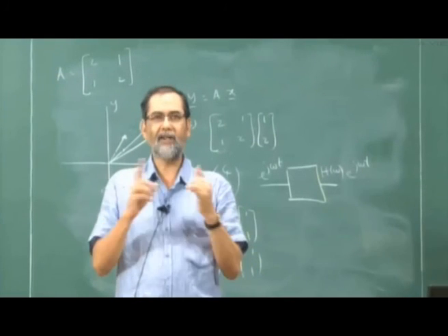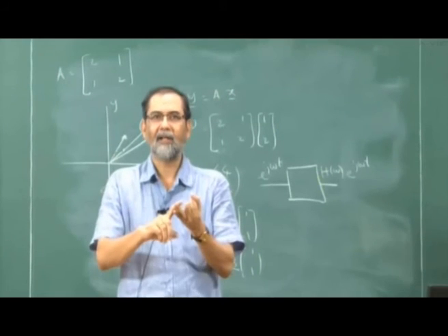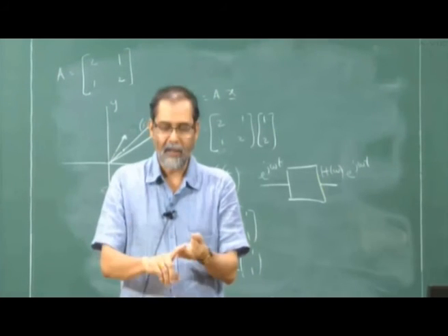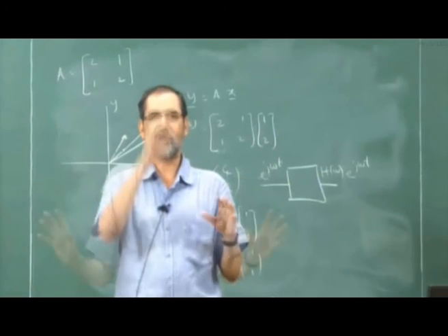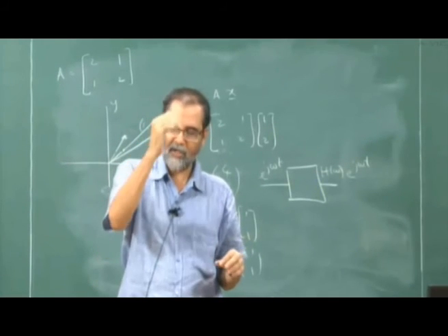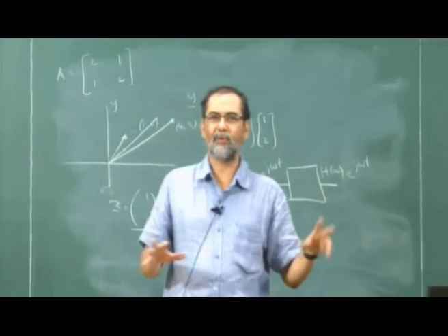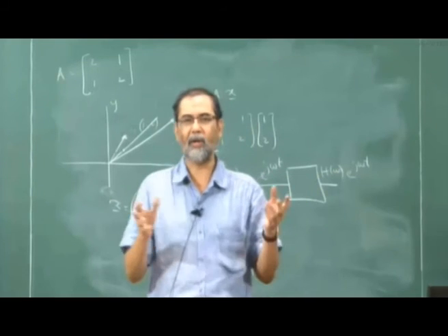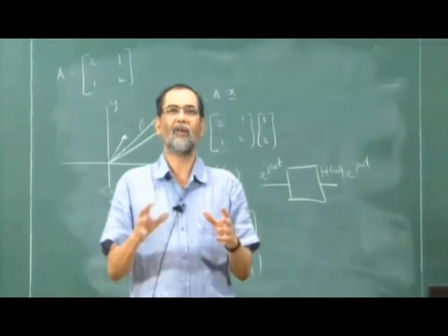No, no, no. First, is the system linear? Is the system time invariant? Then can I give input delta of t at t equal to 0? What is the output? That is the impulse response. So we have to satisfy conditions 1, 2 and 3 to arrive at the impulse response. And you probably can find different ways, but you will have to justify calling it impulse response.